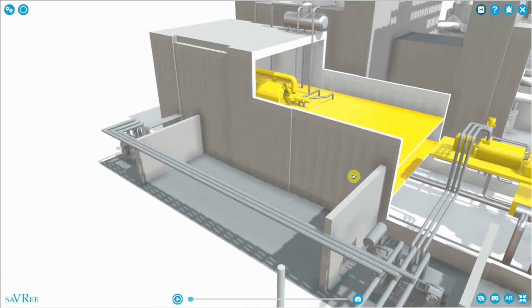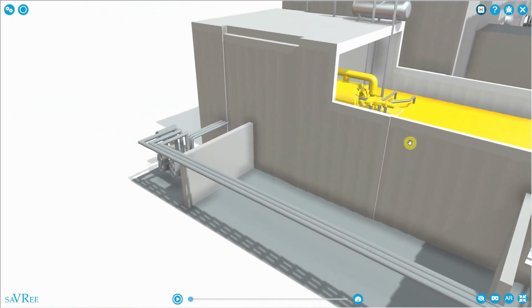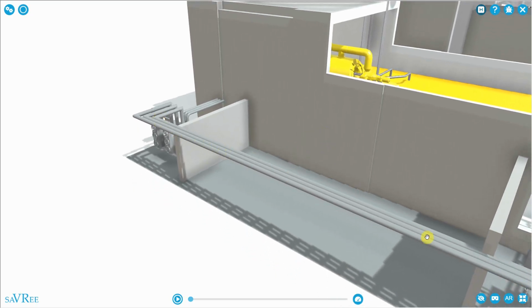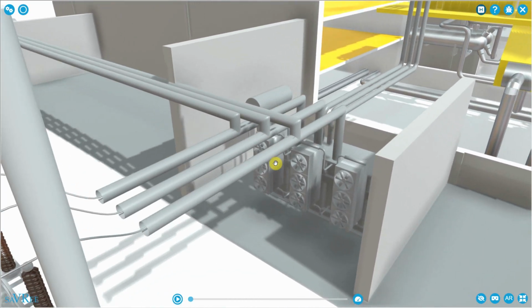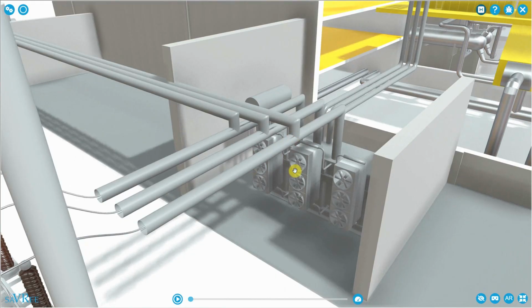However, we could potentially continue generating power within this area where there's another steam turbine, another electrical transformer, another generator, another boiler, etc. We can't do that if we connect this transformer across here onto the same bus as our other transformer. That's why this arrangement is, in my experience, very unlikely.